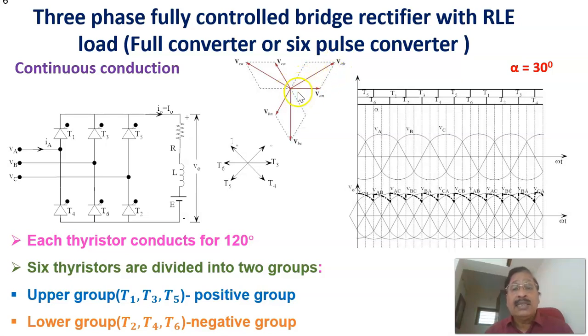One thing you can see is that the line voltage is shifted by 30 degrees from the phase voltage VAN. And one more thing is that the magnitude of the line voltage is equal to √3 times the phase voltage. That's why we can draw the line voltages. This is the line voltage diagram: VAB, VCA, and VBC, like that. These line voltages are drawn below here. These are the line voltages obtained by this mechanism. Of course, the magnitude is √3 times the phase voltage, and there is a phase shift. These are the line voltages, and these are the phase voltages.